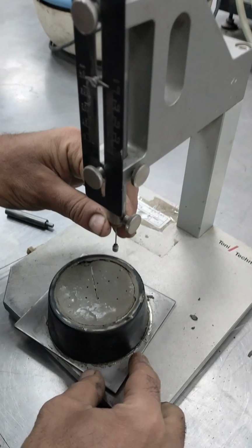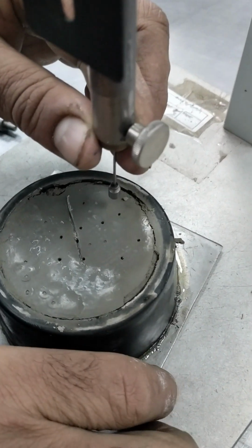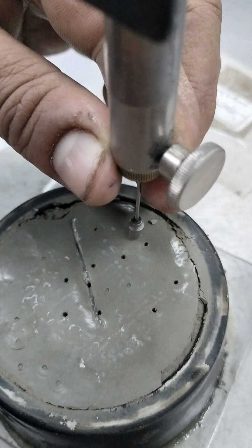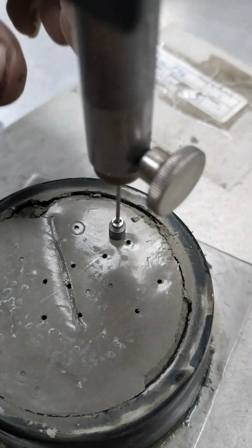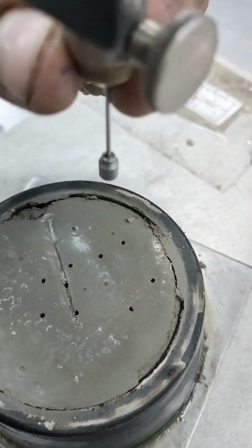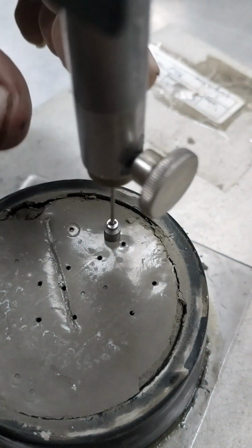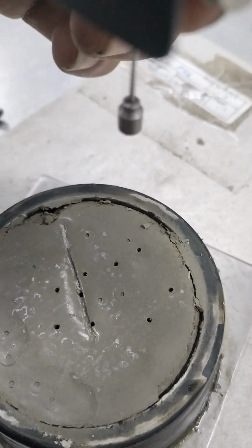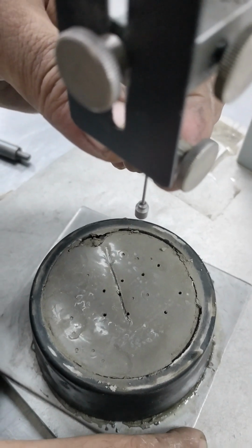Determination of final setting time. After a suitable time, position the mold, base plate and container under the needle of the Vicat apparatus, then release the moving parts quickly and allow the needle to penetrate vertically into the paste. Read the scale when penetration has ceased, or 30s after the release of the needle, whichever is the earlier. Repeat the penetrations on the same specimen at conveniently spaced positions, at conveniently spaced intervals of time, e.g. at 30-minute intervals. Between penetrations keep the specimen in the container in the temperature-controlled enclosure.